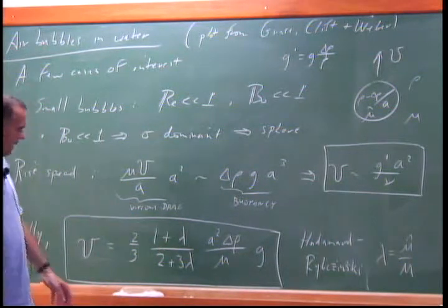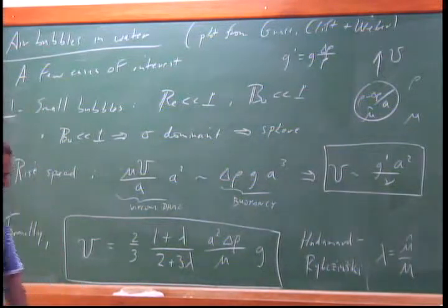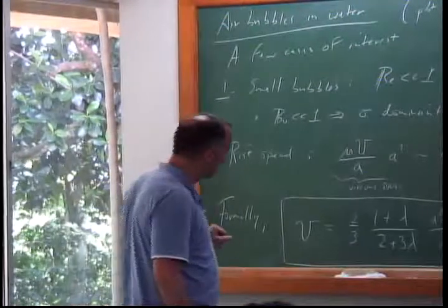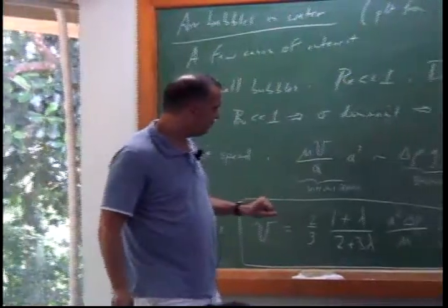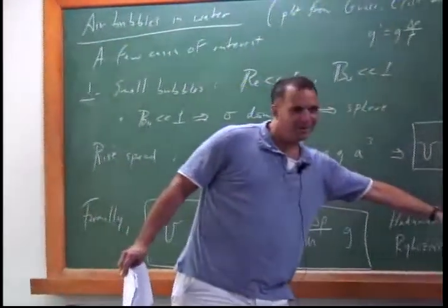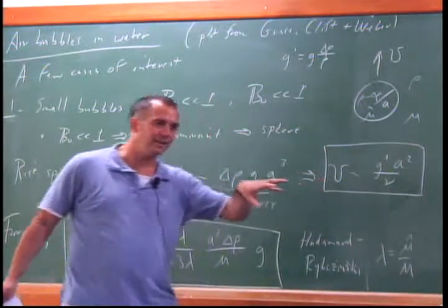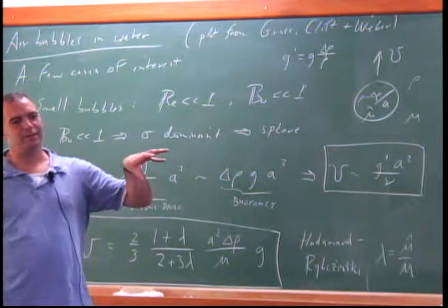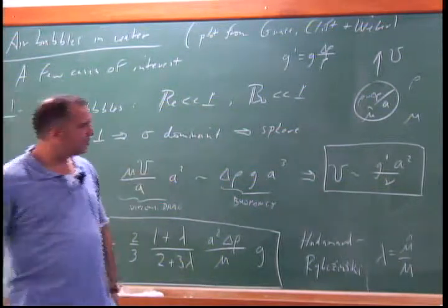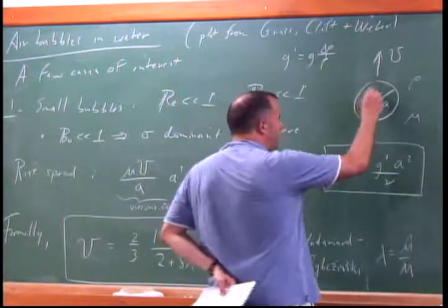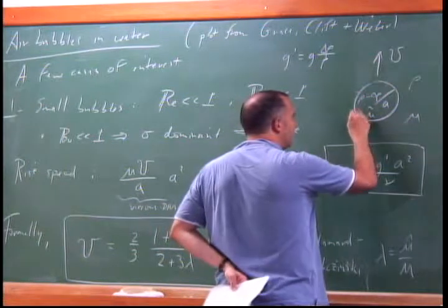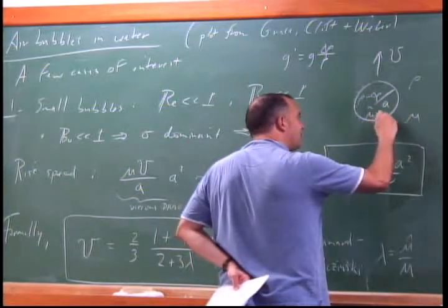Okay, and the other interesting thing of note, and I mentioned this earlier, is that when you look at bubbles in actual experiments, you always tend to find the result that you expect for lambda being infinite rather than 0. It's because the surface is acting as if it's rigidified, and this is because of the surfactants again. So we had that picture where we had surfactants being swept backwards by the flow and accumulating at the back.